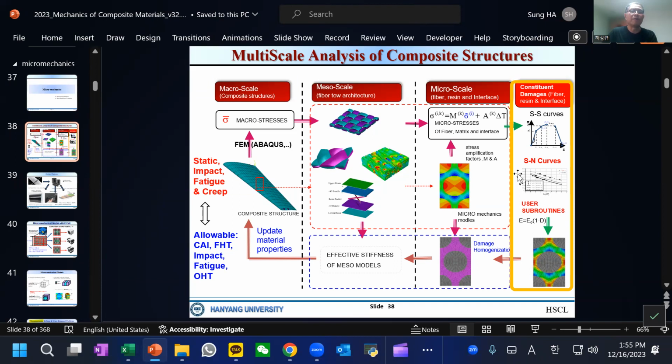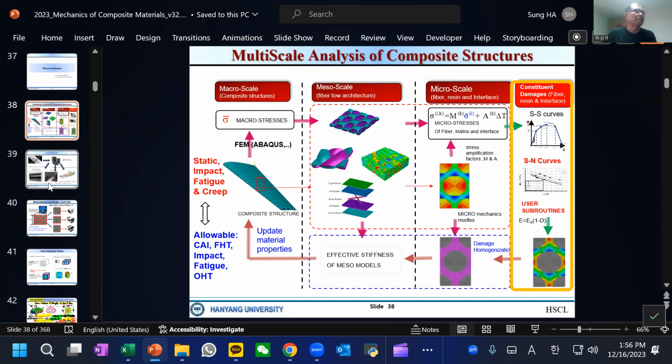For example, under a lot of fatigue load, the overall stiffness will degrade, and then we can get an effective stiffness, and this will change the structural behavior. So this is one example, but again, the conceptual understanding is that the real behavior of the composite is a result of the behavior at the micro levels, like the fiber and resin system, and its degradation.